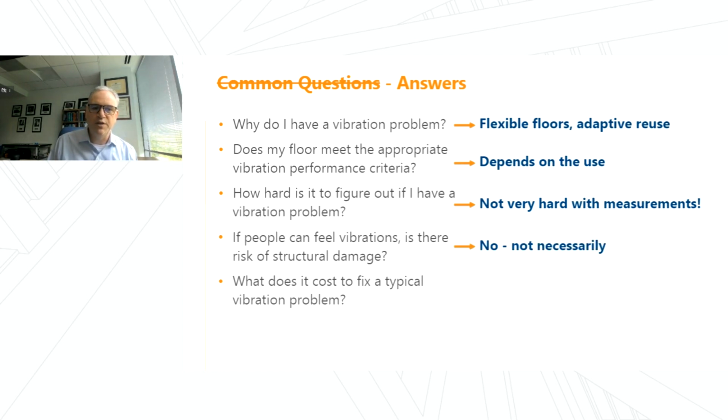If people feel vibrations, is there a risk of structural damage? This does come up, and for the most part, no, not necessarily. Perceptible vibrations are rarely a safety concern, unless we're seeing motion levels on the order of seismic activity. Generally, this is about comfort or equipment performance, not a sign that the building is unsafe.